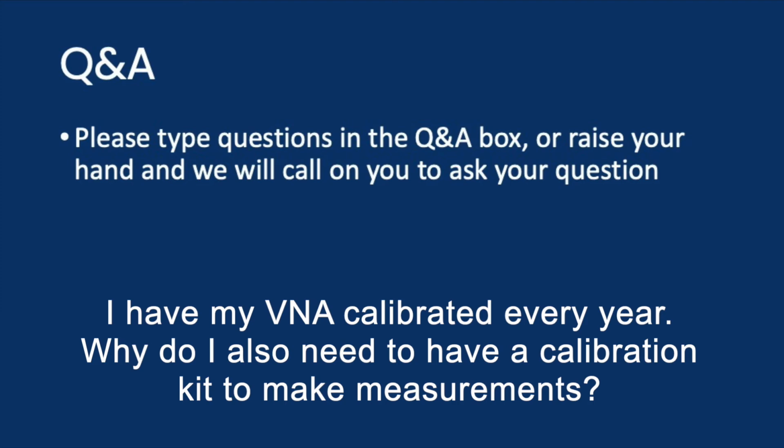Because any and all of those components are going to affect the amplitude and phase right at the measurement plane, the plane at which you want to insert your device and test it. So that's why we need these daily calibrations just to remove these unwanted reflections and remove the extra attenuation that is caused by intervening cables and things.